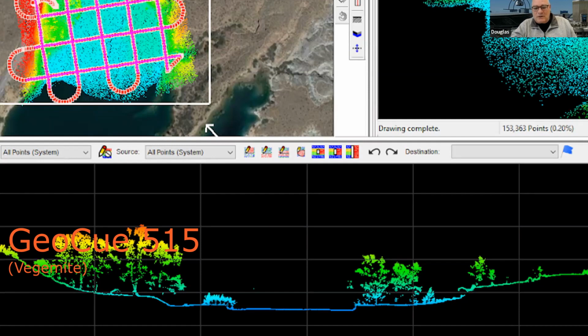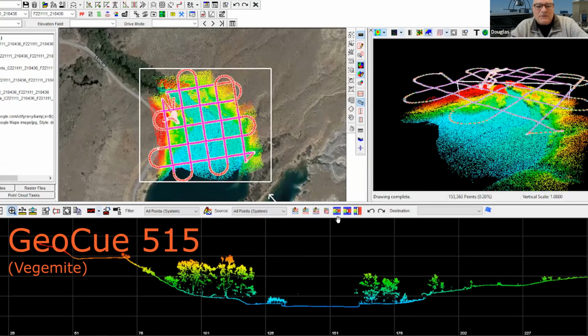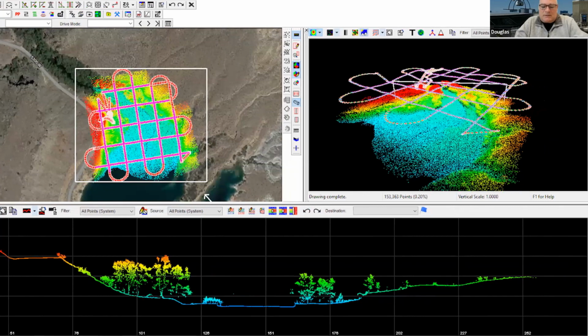But what we can see is where the very edge of the riverbank is right here, and same thing on the other side, and we can even see overgrowth where we've got plants that are growing into the water right there. So that's really the benefit there, this system is very clean. And notice that the strip alignment that we're seeing up here is very, very clean. That's the flight path of the aircraft. And again, we see that down here as well. So we've got a height map that's generated here. This heat map indicates the height of the various foliage that's around. The area that we see in blue is where the river is. If we had not been running the secondary camera there, that blue would just show up as a solid black. So let's step on to another system here.